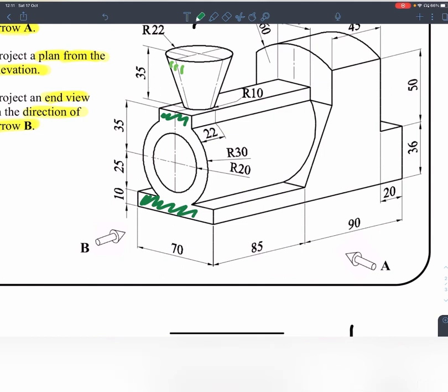So what I'm going to do is just finish off the circle, and you'll be able to see it more clear that it cuts into these sections. Okay, so when you're drawing this, we will draw a construction line for the circle, draw this section in, and then harden in the circle after we've drawn the two sections up the top here. Does that make sense to you?